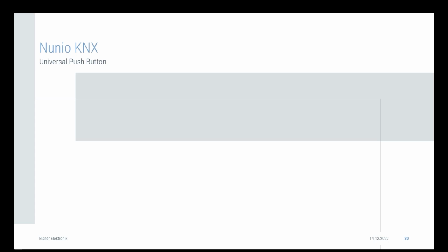There has been another comment. So if the installer wants to use only 2-point control, activate two-level heating and set the offset to 0. Thank you for the comment at this point.